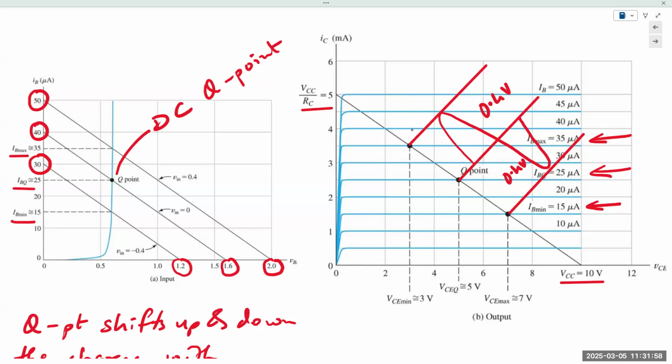Look at the corresponding IC. As I said, the coordinates of these intersection points give us our solution. So that's 0, and IC swings between what? 1.5 milliamps and 3.5 milliamps. So this would be 1.5. So it would be 3.5. Okay. And obviously the numbers here, it's a problem, so it's nice round figures. You got input of 35 microamps, you get 3.5 milliamps. Obviously, real life experiments would never work with these kind of numbers.